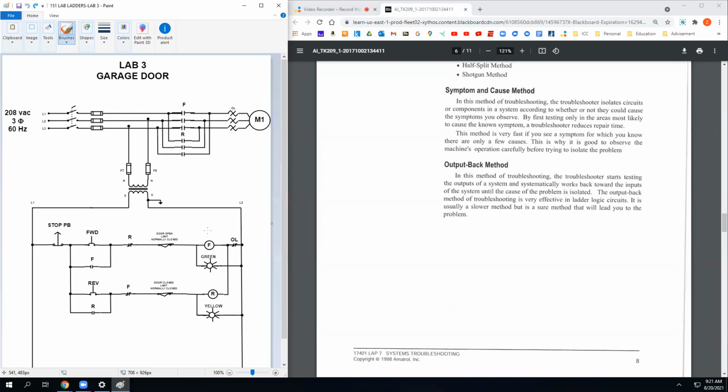Where? Motor wiring. The motor windings? Yeah. In here? And to turn the motor backwards or forwards, you have to switch two of the cables, right? Yes. And where does that happen at? It happens right there. Yes, sir. Okay.